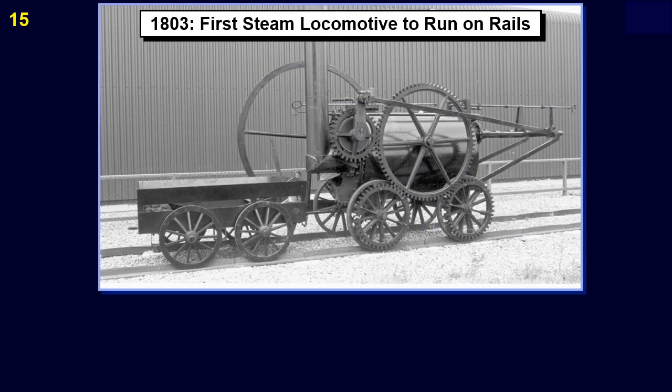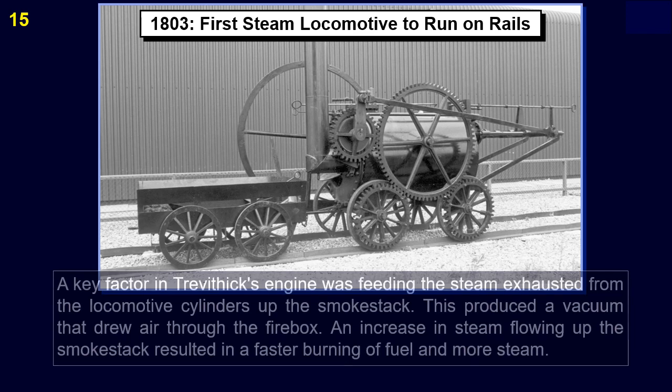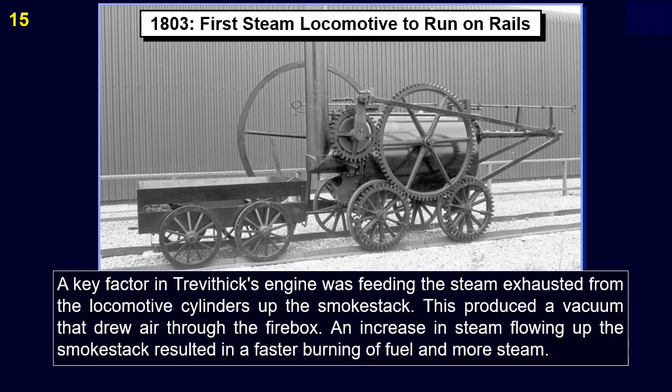A key factor in Trevithick's engine was feeding the steam exhausted from the locomotive cylinders up the smokestack. This produced a vacuum that drew air through the firebox. An increase in steam flowing up the smokestack resulted in a faster burning of fuel and more steam.